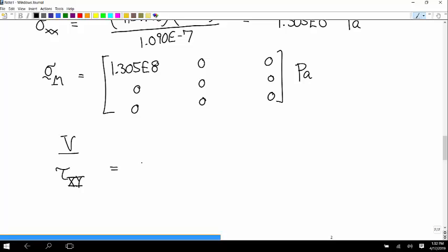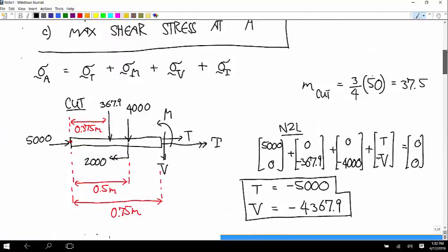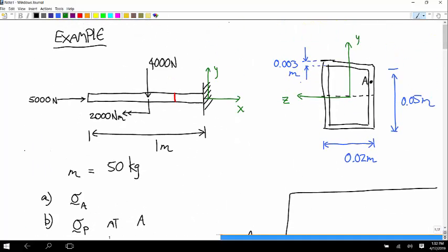And the shear stress is negative V times Q divided by I times B. That always has the z-axis pointing out of the wall. So in this case, that would be like rotated this way with your capital Z-axis like this, your capital Y-axis like this. And then we'll have to use a rotation matrix to represent it in the coordinate system we want.